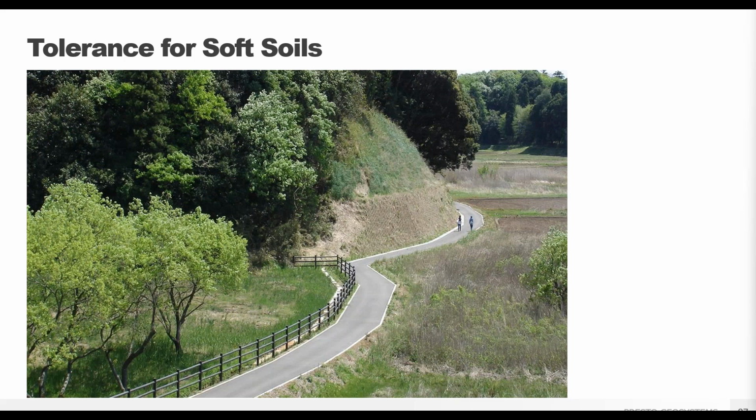Using the GeoWeb system can help avoid expensive and time-consuming activities such as surcharge loading a site, which often has to happen when differential settlement is a concern. The time required for the surcharge loading may be reduced or even eliminated when using a GeoWeb wall. It also reduces the amount of visual inspection maintenance and repair over the lifetime of the wall structure, since the GeoWeb panels can accommodate much more movement than any masonry wall could.